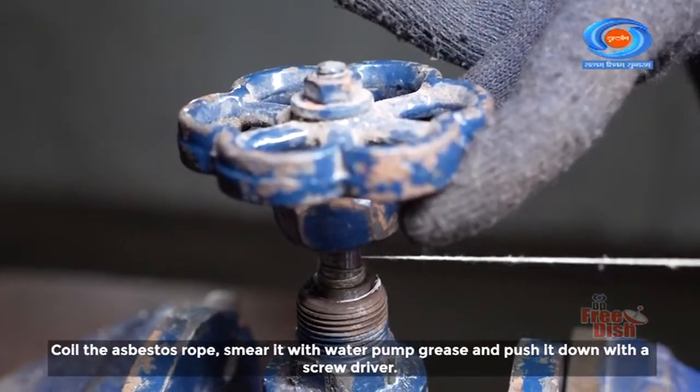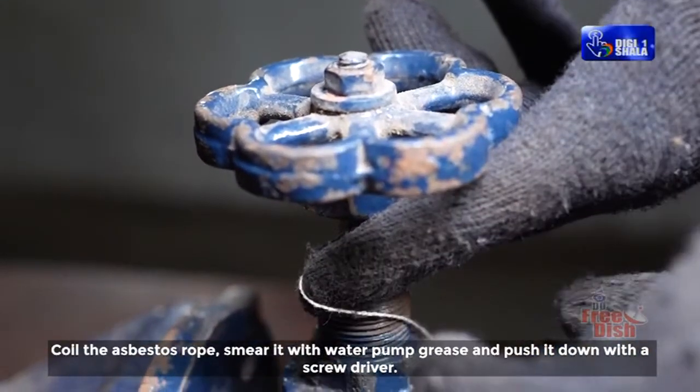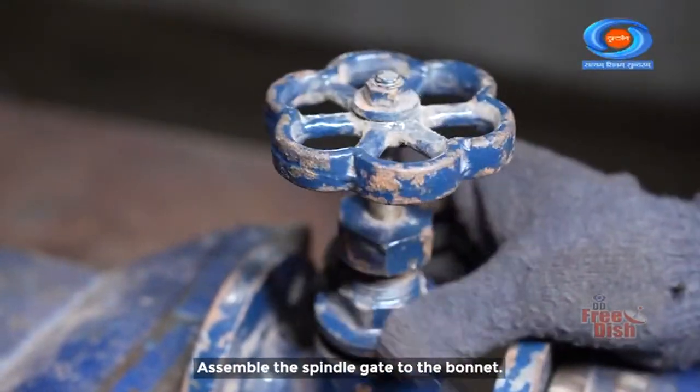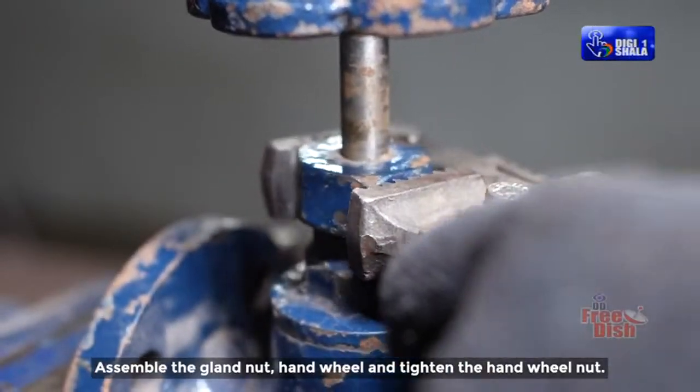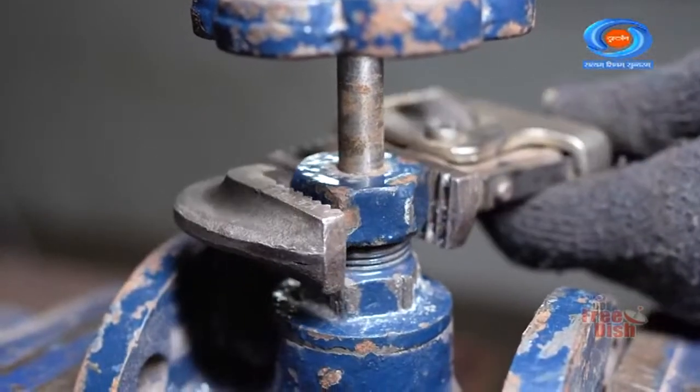Coil the asbestos rope, smear it with water pump grease and push it down with a screwdriver. Assemble the spindle gate to the bonnet. Assemble the gland nut, hand wheel and tighten the hand wheel nut.